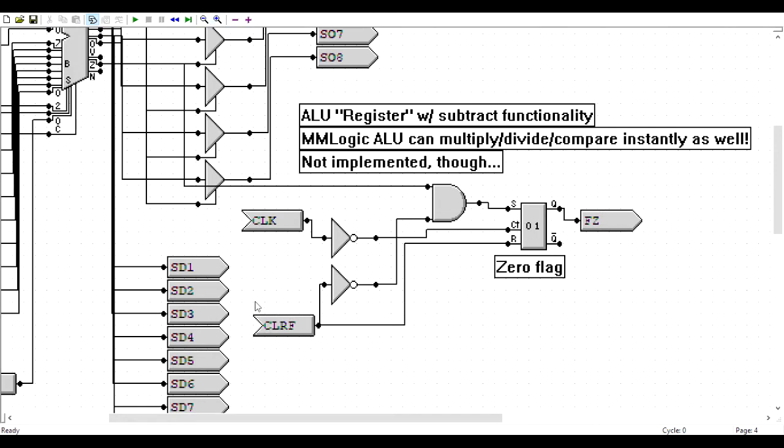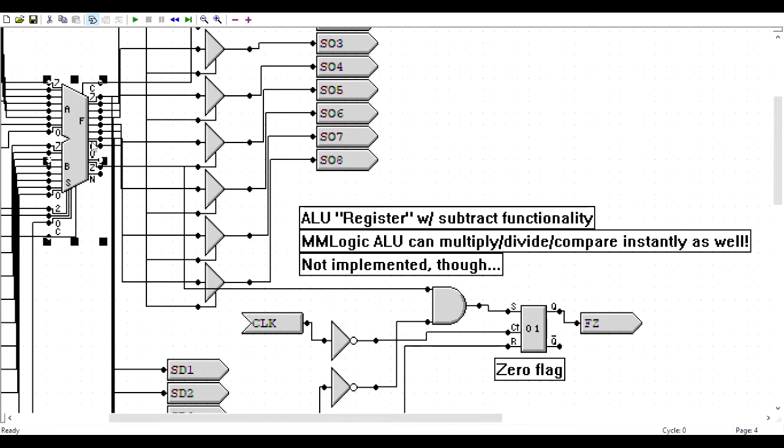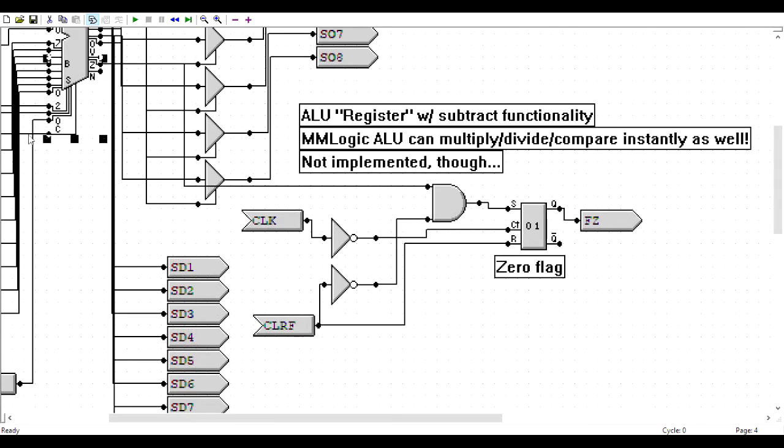What happens is that we have a clear flag bit, which is one of the words that we set in the microcode logic, which activates whenever we are using an instruction that is going to affect the ALU, namely LDA, add, and subtract instructions. It is in that time that we are looking for a chance to see if the flip-flop is going to get updated.